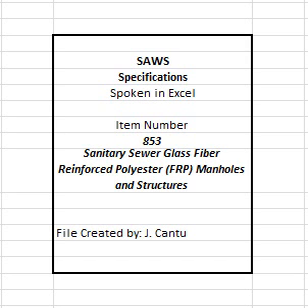7. Marking and identification. Each piece or component of the manholes and structures shall be marked in letters no less than 1 inch in height with the following information. Markings shall be legible and located in a place within the manhole or structure. Tag and slash or stamp shall be placed in a location that can clearly be seen within the manhole or structure. Manufacturer's name or trademark.